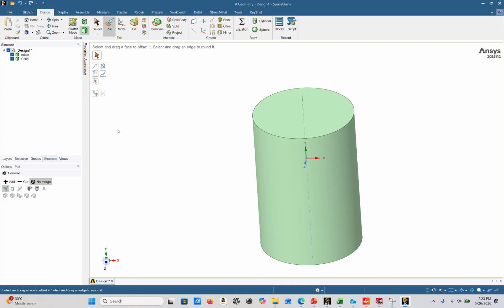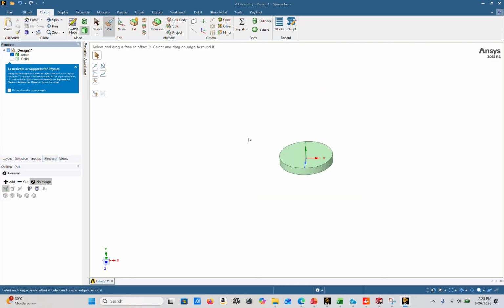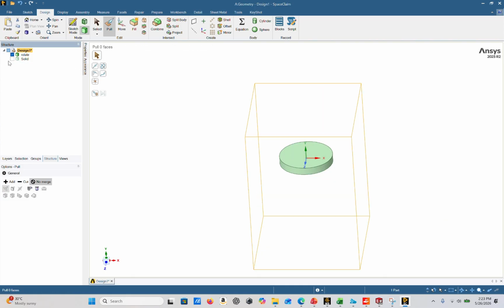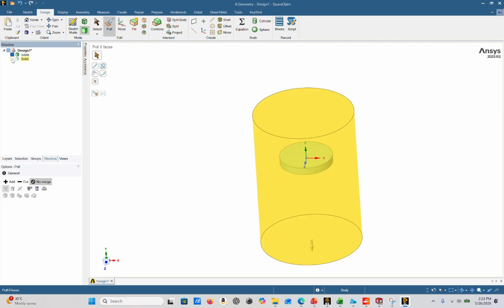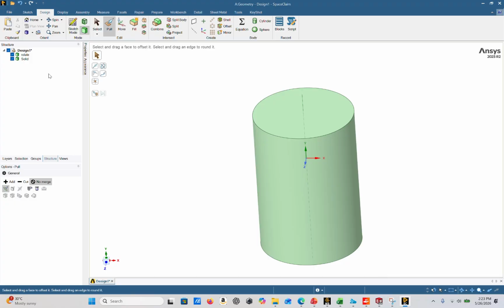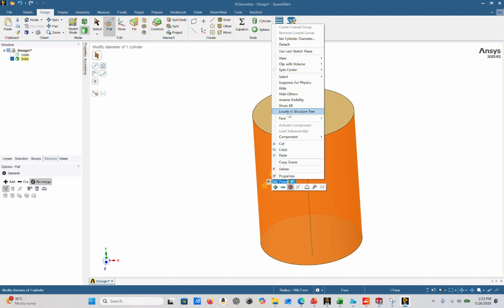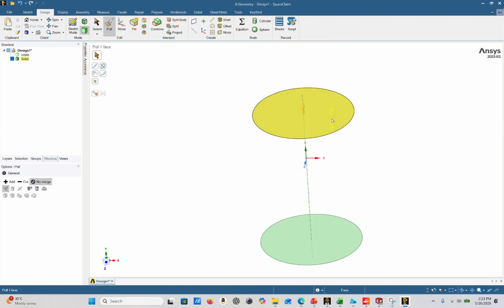And right now we want to make sure that the rotating domain has space, and you can clearly see how we can close and open, so we can see by just ticking and unticking to make sure that what we're doing is correct. You want to again make sure that the rotating domain is deleted from the inner domain's body, so the rotating domain itself can fit inside the inner domain, as if there's space for the rotating domain.